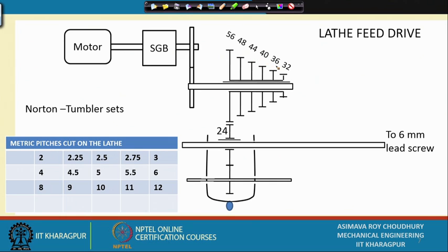Now, why are we doing this? We are doing this with a particular purpose. The purpose is this: on this side we have another gear which can be preferentially or selectively connected with either 56 or 48. So, this 24 gear can be connected with 56, it can also be connected with 48, but obviously center distance is going to be different, because these two shafts, this shaft and this shaft, they are fixed. How can I attach 24 selectively and sequentially to these gears?